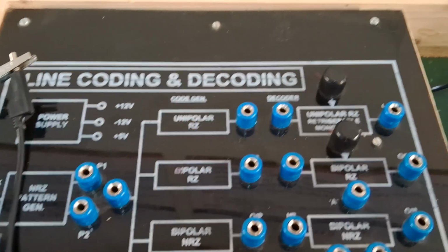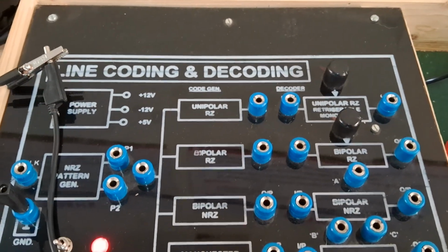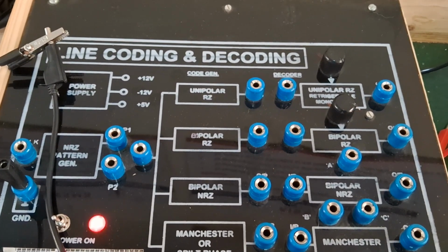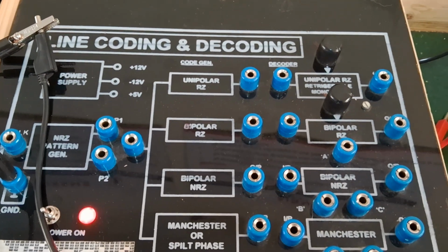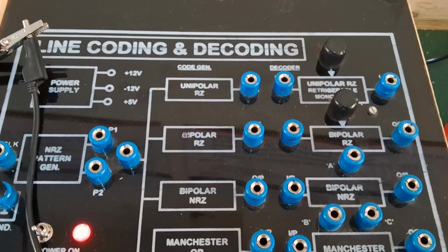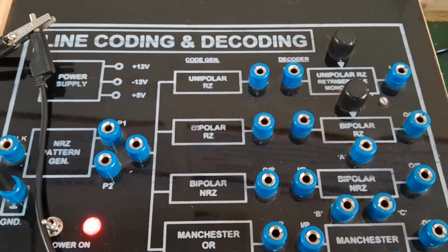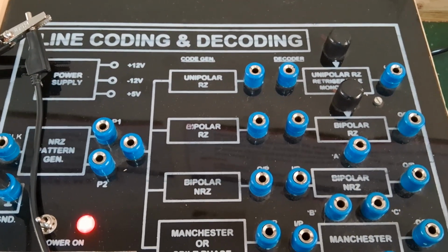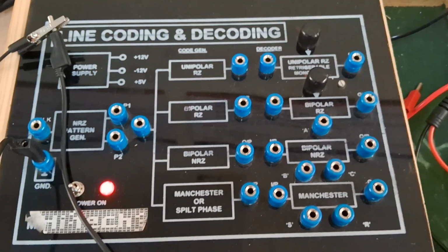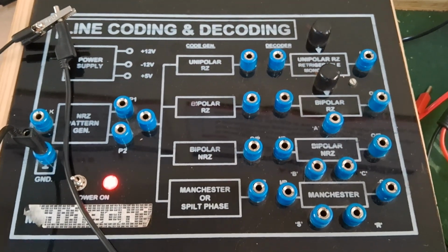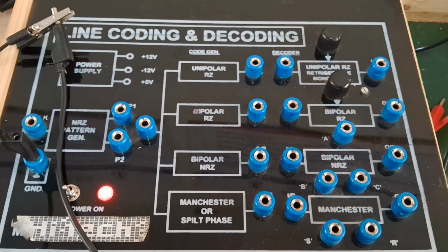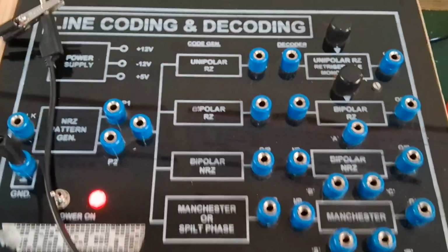Okay, here we are now to learn line coding, which we also call data formats. Data formats are the different formats used for digital data, so that if there are any errors at the receiver side, they can be detected if you convert into a typical format. The properties of the data formats are designed in such a way that the bandwidth as well as the energy required for the signal is maintained during transmission.